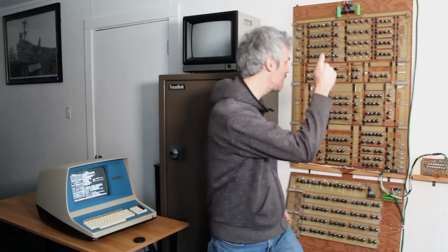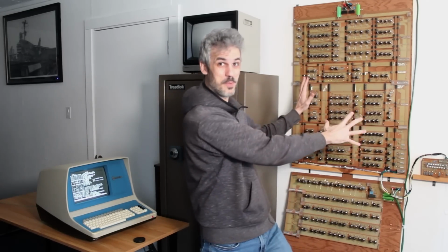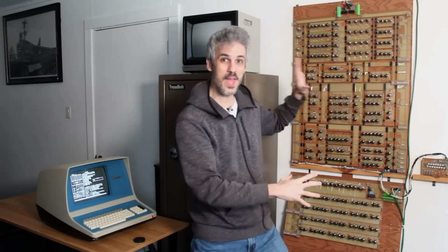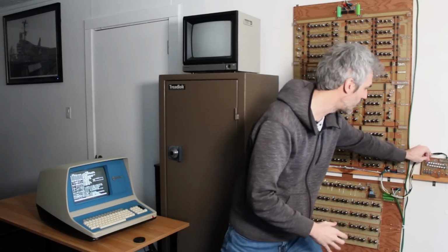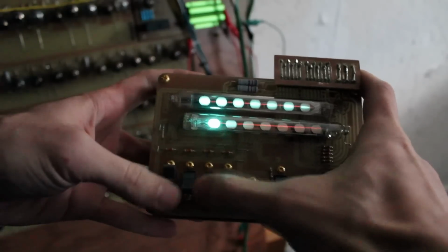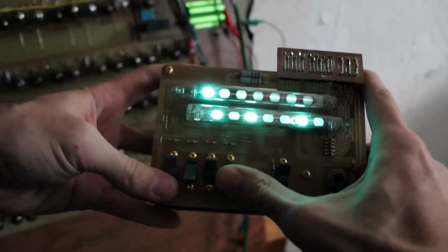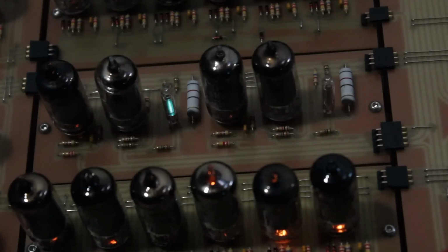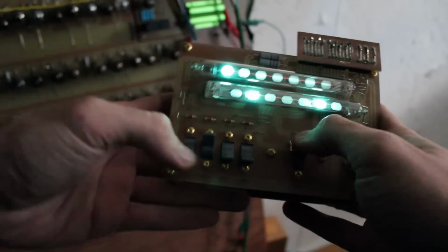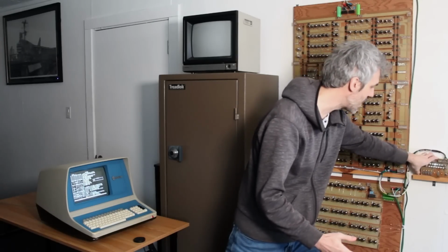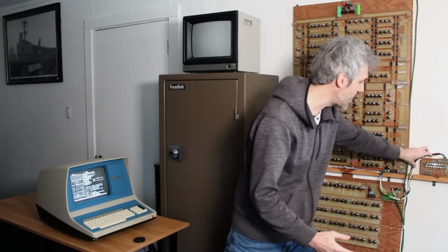How cool is that? The real vacuum tube computer is on because I've been using it as a heater for the room. So we'll go ahead and initialize it. I've got the little remote control for it over here. So we'll do a 1010, force the data to 1. That should put a 1 in the IEN register there. We'll do the same for OEN down here. And then we'll do a 0100 to put a 1 there. And then we will load a 0 into that. And there we go. The vacuum tube computer is now fully initialized and ready to go.